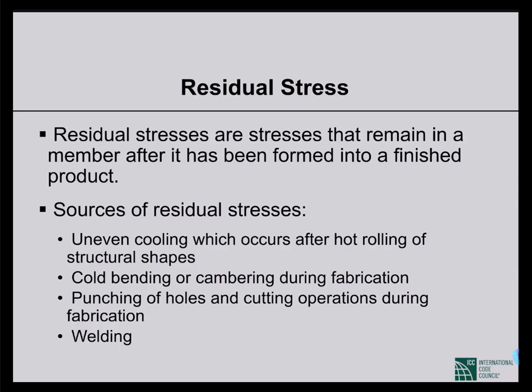The member may be produced at a site. Whatever be the case, in the finished product, if we have stresses within the member, even without applying any load, if there are trapped stresses, we call them residual stresses. Now, what are the sources of these residual stresses? The most important source is the first one, uneven cooling.